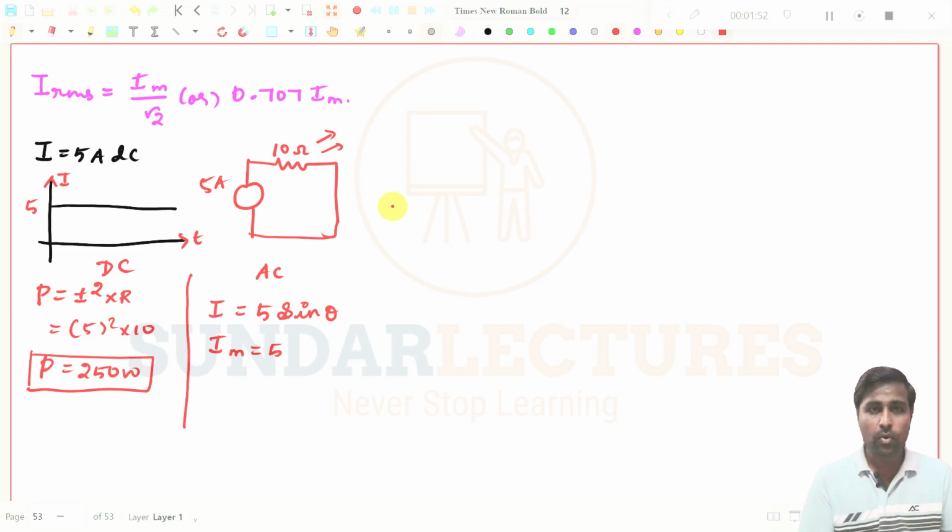Now, if you want to get the power value, you need to get the RMS value, as I have already told you. So IRMS will be equal to maximum value Im divided by root 2. So this will be 5 divided by root 2, right?